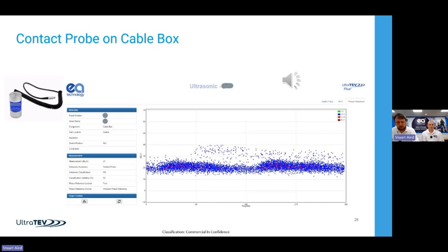So it's the first one of our demonstration, and it's the least clear, hopefully, you're going to hear today. The audio file for this isn't particularly clear, but there are signs in the phase plot that this looks like PD. There's this clustering going on, and there's our classification there. So, question to yourselves, with that information in front of you, would you be thinking of taking an outage? There's a quick poll, I believe, that's been pushed out on that.